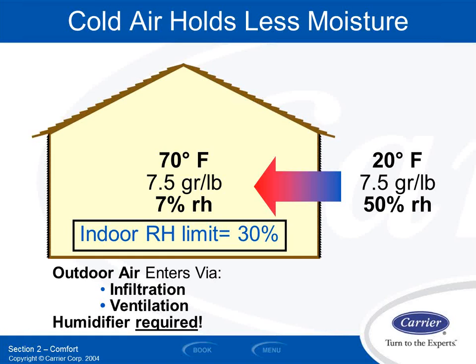In some of these kinds of cases, if you have dry air like that in your house or your building, you may need to add humidity to it with a humidifier. It doesn't happen a lot residentially because there are so many occupants in the building that generate moisture as well. But if it's certain types of spaces where I have electronics or wood products or things like that, then I typically need to do it more. The looser my building is and the more outside air I leak in, the more likely I am to need a humidifier as well.